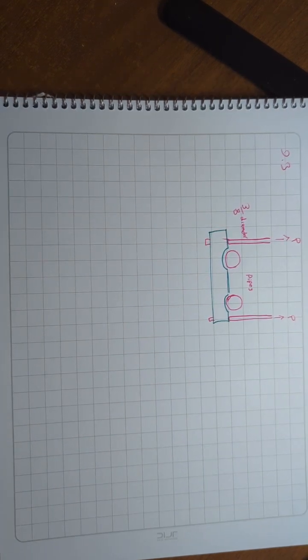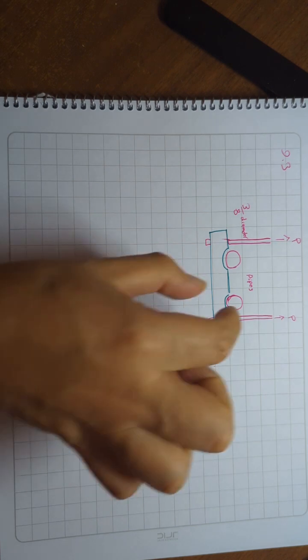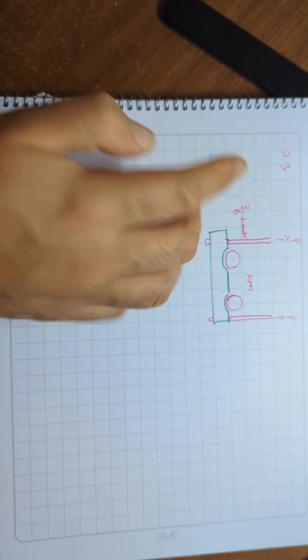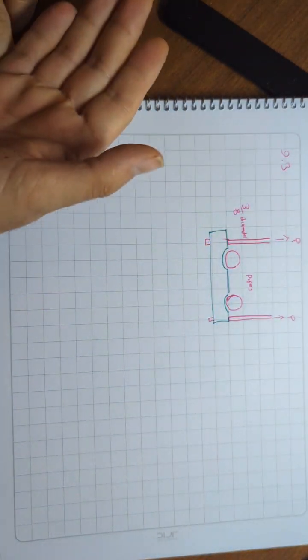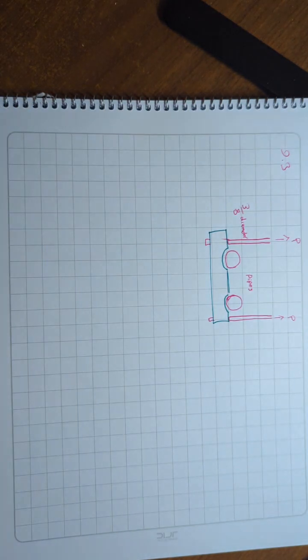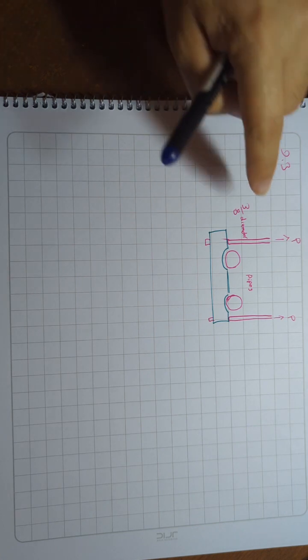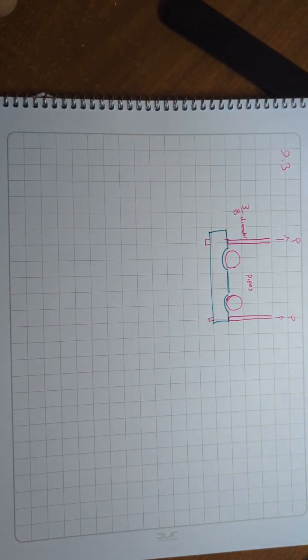Okay, example 9.3. The steel rod suspenders are to support pipes in a power plant as shown in figure 9.4. So these are two pipes, and this is the steel rod supporter that holds these two pipes. Just remember, this is the cross section, okay? Each rod has a diameter of 3/8 inch and has an allowable axial tensile stress of 24,000 psi in the body of the rod. Calculate the allowable axial tensile load in each rod.